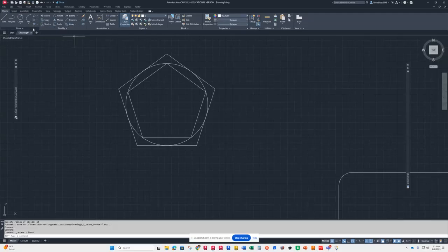All right, so now you've got two or three more commands in the draw area. This is an ellipse, and you can draw an ellipse, very simple, from a center point. So you draw the center, then you draw half of the major axis, so it has a major and minor axis. Major is bigger, minor is smaller, obviously. And then you do the vertical axis, half of it.